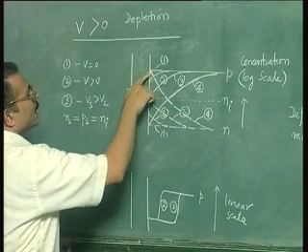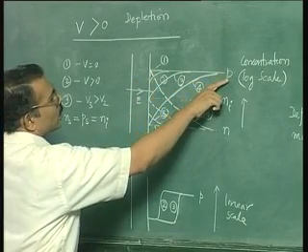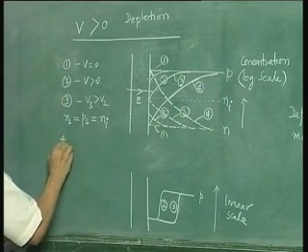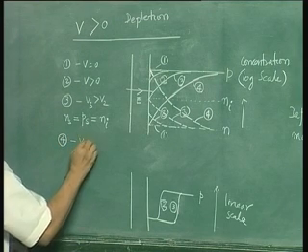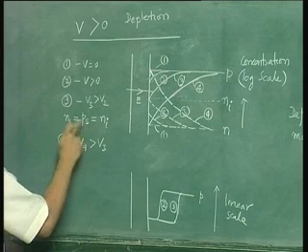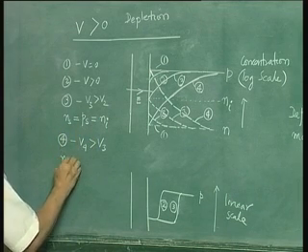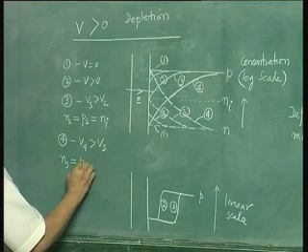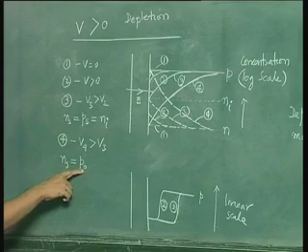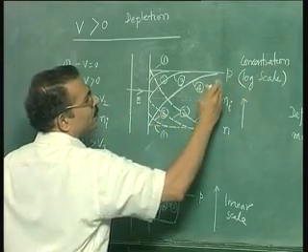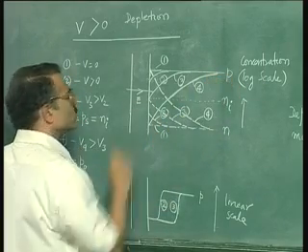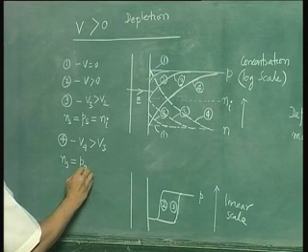This means that Ns is equal to P in the bulk. Condition 4 is when the voltage is more than the voltage for condition 3, and the condition on concentrations inside is that Ns is equal to P naught, where P naught refers to the hole concentration in the bulk. Bulk means this region inside here away from the interface, where the concentration is decided solely by doping and there is no electric field. So this P naught is the bulk concentration.